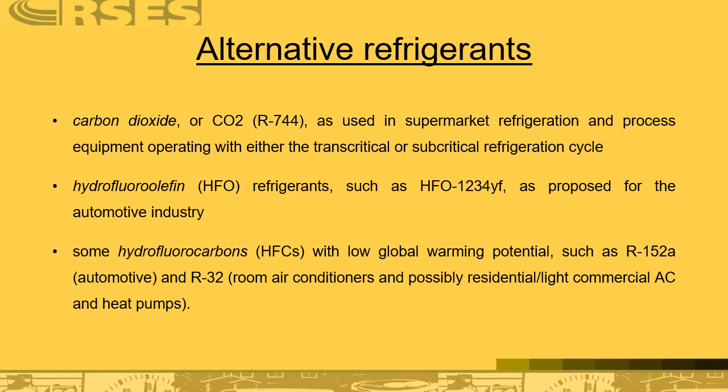Hydrofluoroolefin, HFO, refrigerants such as HFO-1234yf are proposed for automotive. That's in use now. There are also some hydrofluorocarbons, HFCs, with low global warming potential, such as R152A for automotive, and R32 for room air conditioners, and possibly residential and light commercial AC and heat pumps.